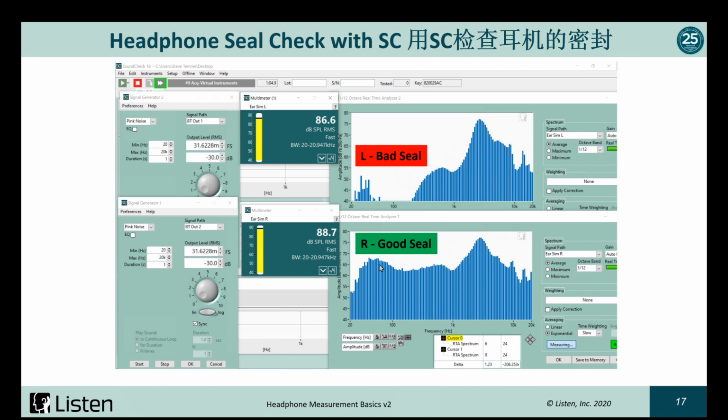And it is kind of a relative measurement, and you just kind of have to sit there and play around until you get the best possible seal. You may also find, depending on the size of the headphones, like I mentioned, the intraconcha, the ones that sit on top of the pinna but not circumoral, the high frequency will depend on the positioning on the pinna as well. So I always recommend doing this first before you make the complete measurement and measure things like distortion.